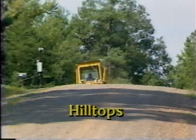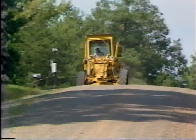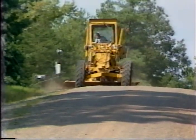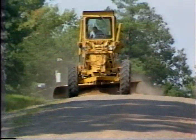Another special condition is machining over hilltops. If the blade height is not adjusted on the grader, this will cause the top of the hill to be cut off. Gradually raise and lower the blade as the grader passes over the crest of the hill.